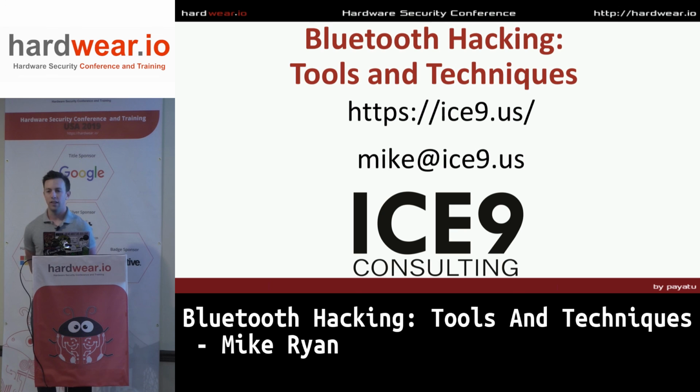And in the case of BLE, you can try your luck with an Ubertooth. I found in practice, if you're not controlling one of the devices, it's pretty hard to actually successfully sniff. You have to capture the initial part of the connection. And if you miss that, yeah, it's troublesome.